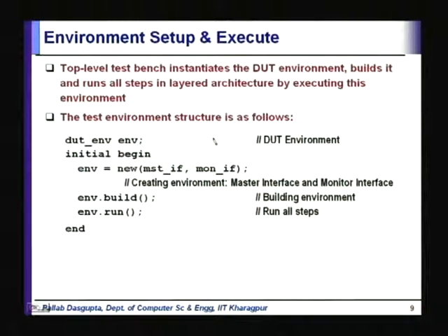Now this is the top level thing that we do. I am starting from the top, and then we are going to dig into each of these things. The whole thing is going to run in the initial block. In the SystemVerilog test bench, it is in this initial block that we call these tasks, and once these tasks are executed, we are done. There is nothing else in the test environment. Everything is within these tasks.